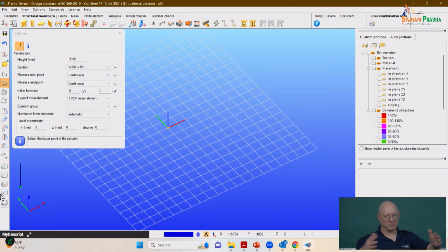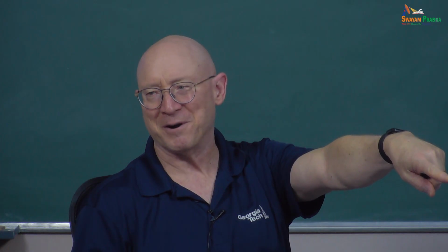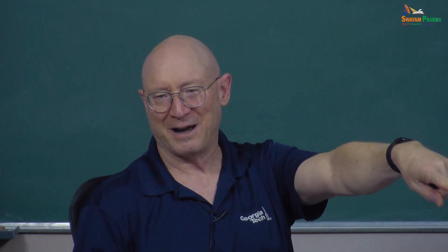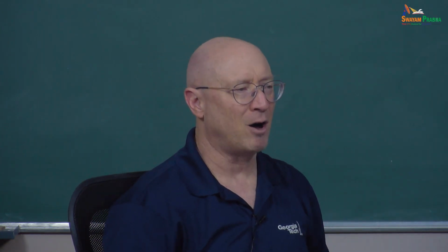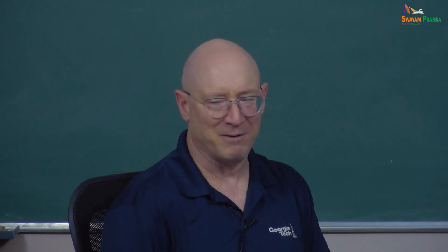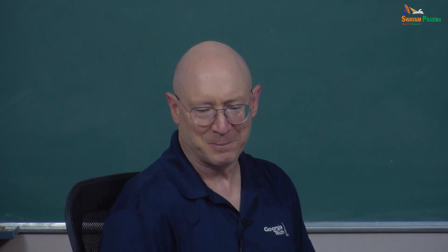So I basically say, I have a girder that goes 200 feet. I've got various members connecting into that girder. I draw the whole girder. I draw these other members. Consteel recognizes, these come into the same point. I'm going to put a node there. So I never have to actually explicitly define that node. So hopefully that gives you that feature of pretty much drawing members. Everything's member-based. And then the connectivity, you can control that, but it's very efficient in terms of being able to create your models by having that scheme for doing things.